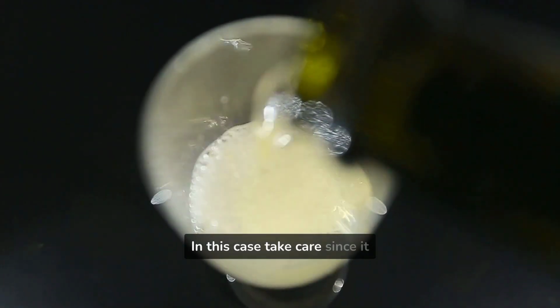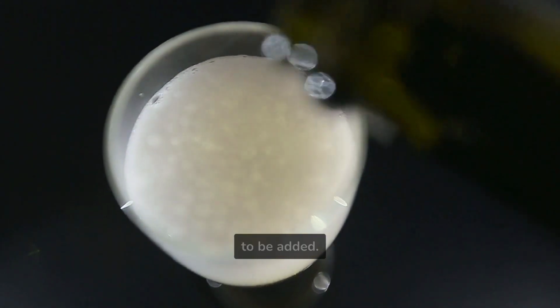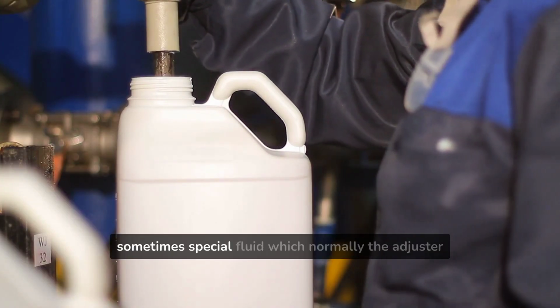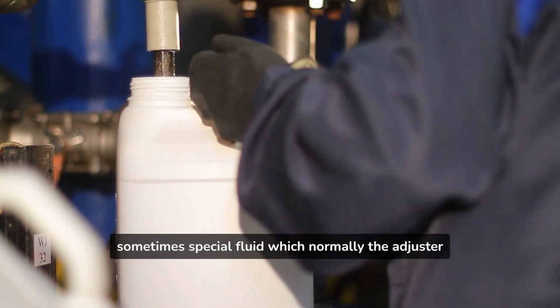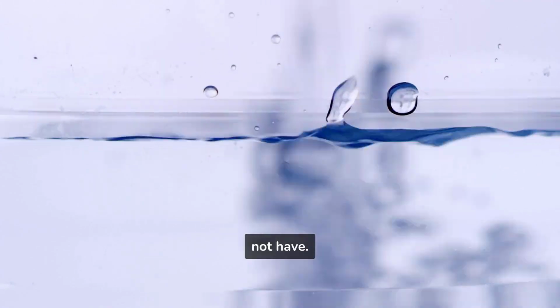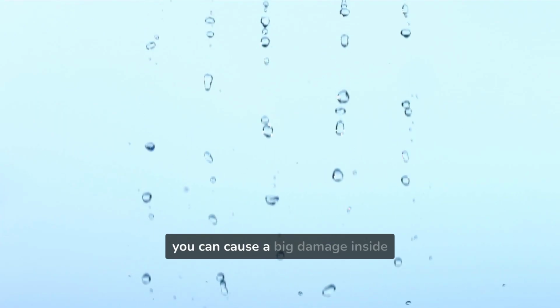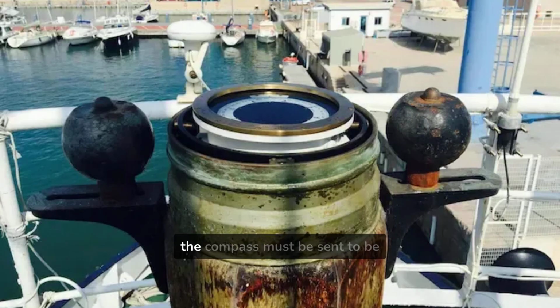In this case, take care since it is important to know which one is to be added. Sometimes distilled water, sometimes special fluid which normally the adjuster, if it was not advised, he will not have. If you fill with an inappropriate fluid, you can cause big damage inside the compass. If the bubble is big, the compass must be sent to be repaired since the membrane or any seal gasket is damaged and the compass is leaking.